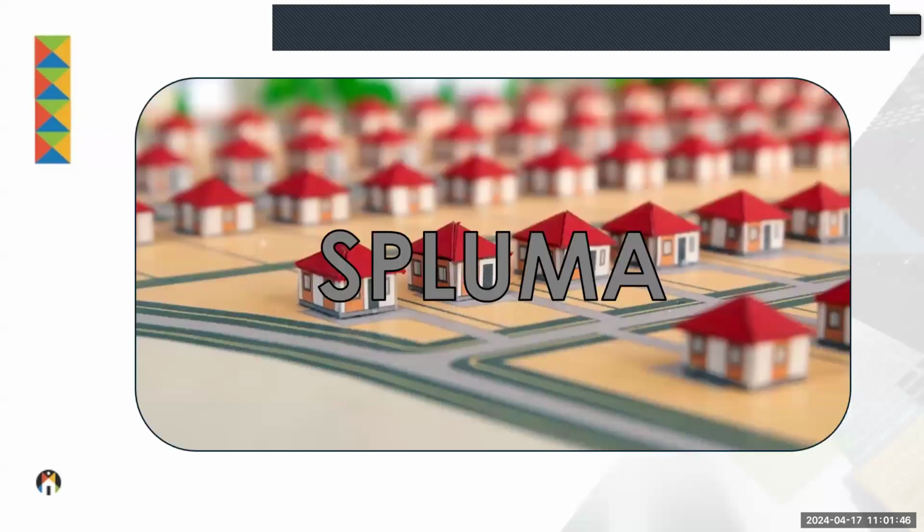So that's why I brought those two things up, so that we just have to understand that, yes, we've got a legal duty imposed on us by our code of conduct to comply with the building regulations, SPLUMA, and other legislation, although it might not be checked by local authorities for plan approval purposes. And also that we need to know the time constraints specifically, and how long certain procedures will take for special consents, building line relaxations, zoning applications, etc.